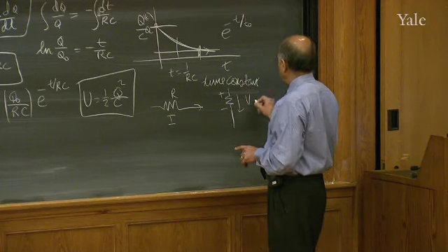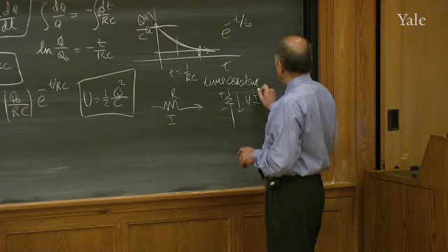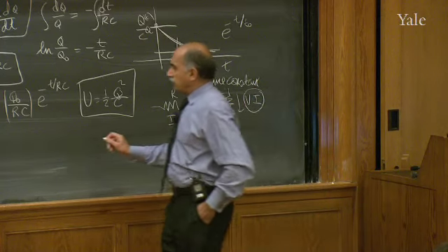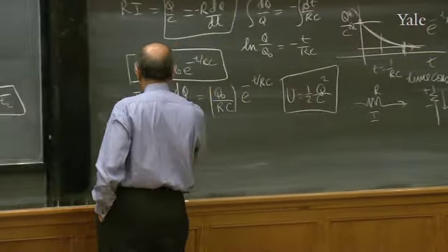Therefore, in 1 second, the number of coulombs falling down is I, and the energy is VI, and that's the power. So power in a resistor is VI. That's the rate of energy consumption.